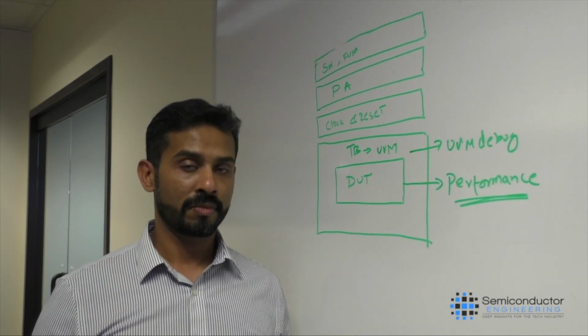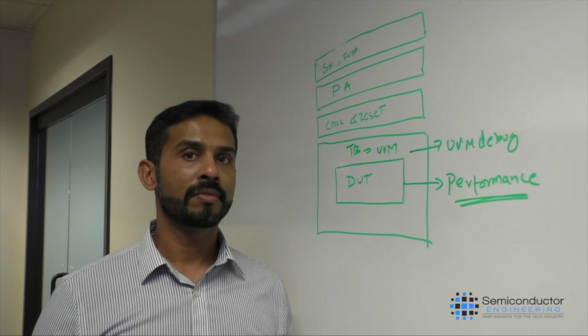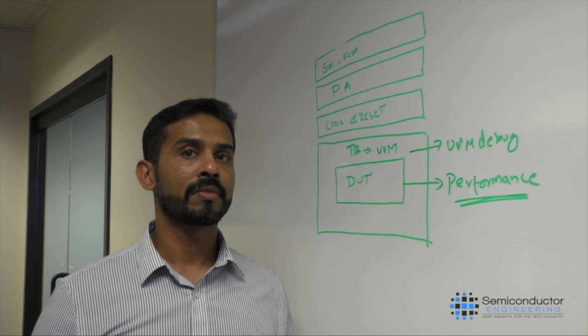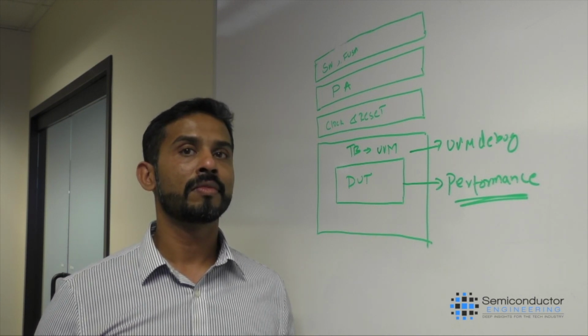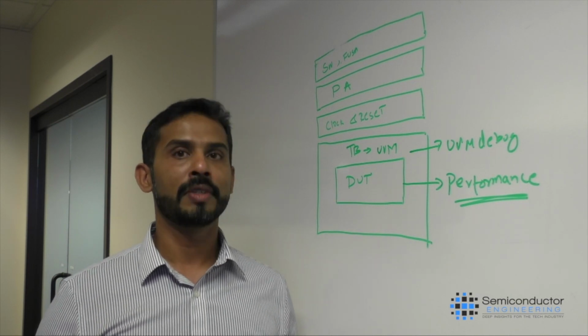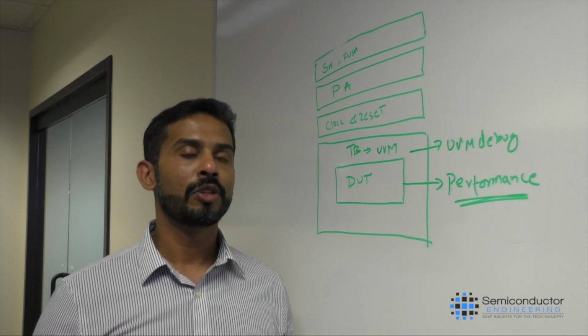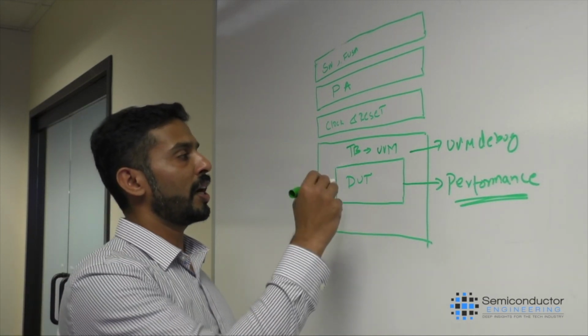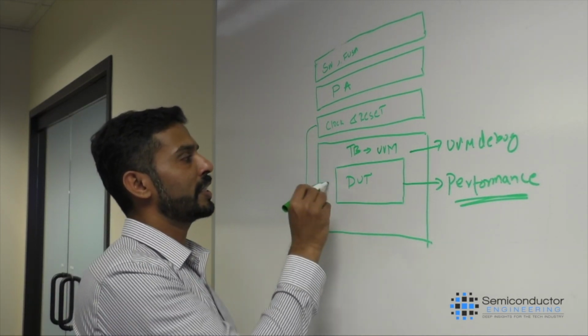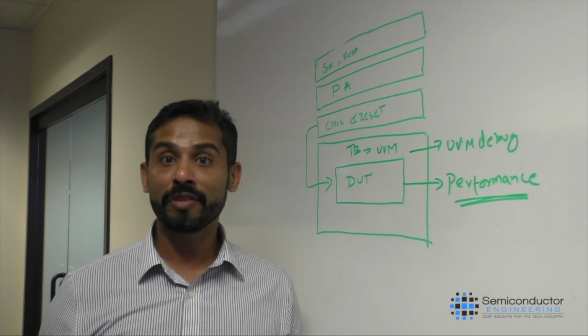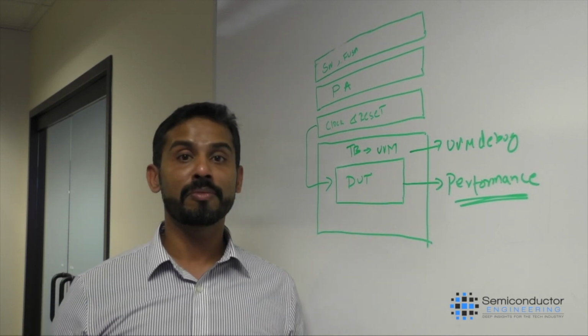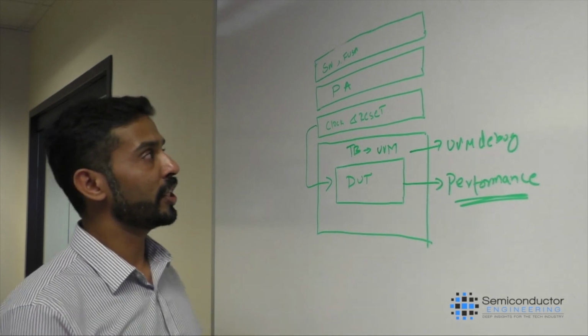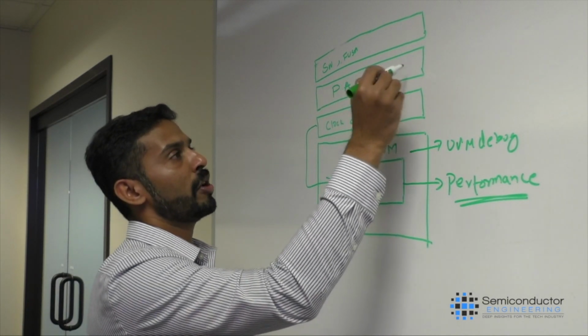They have a lot of clock domains. They even have a lot of power domains. All this stuff is setting in motion things like it's on, it's off, it's not quite on. Well, how does that affect what you're debugging? So if you look at a design this size, there are clock and reset domains, and designers are grappling with this, right? So they have multiple clock domains, multiple reset domains, and to add to this, you have power aware.